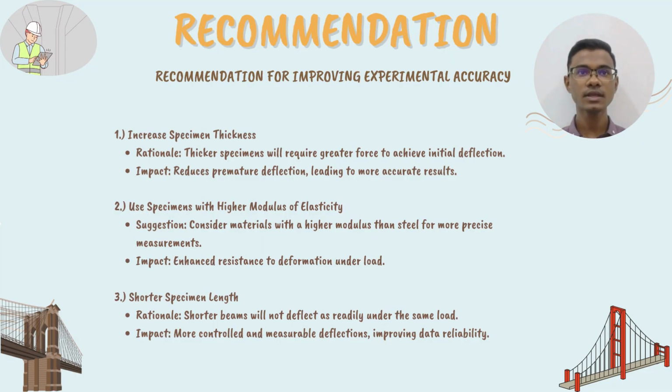Last but not least, the recommendations for improving experimental accuracy. The first recommendation would be to increase the specimen thickness. Rationally, a thicker specimen will require greater force to achieve initial deflection. The impact would be that it would reduce the premature deflection, leading to more accurate results.